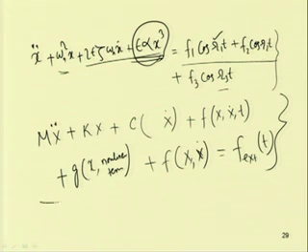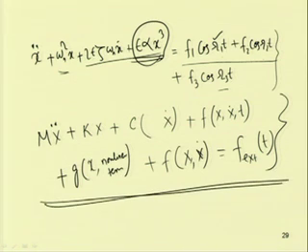So, in this way one can write the equation of motion for a multi degree of freedom system. Then one can reduce this equation by using a modal reduction method. There are several modal reduction methods available, and then one can use this ordering technique to order these equations. After ordering these equations, one can then go for the solution technique, which we will discuss in the next module.